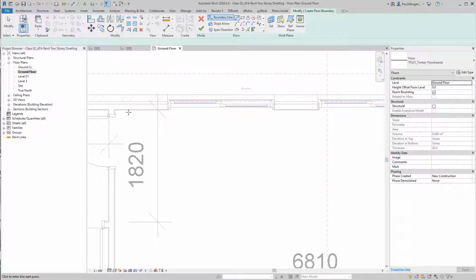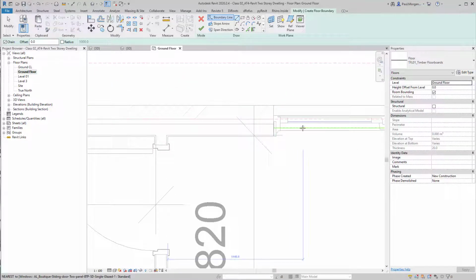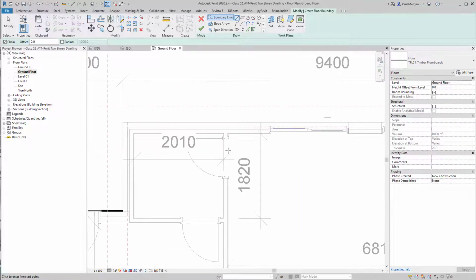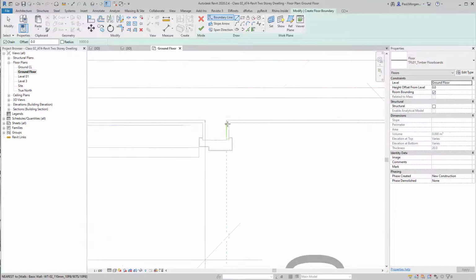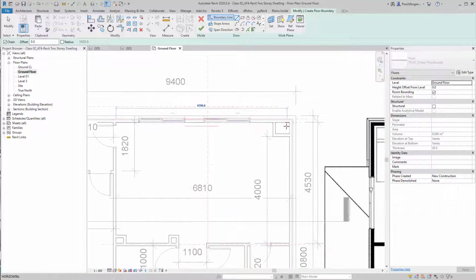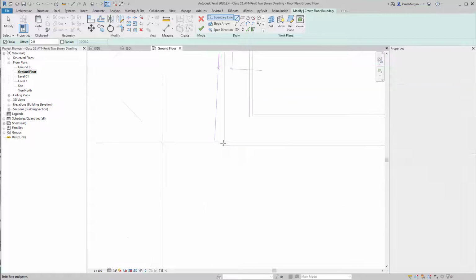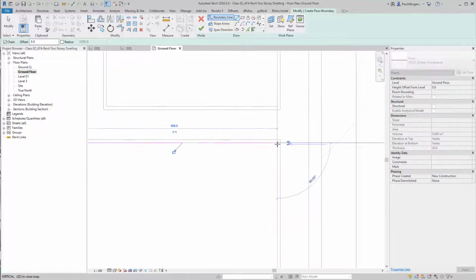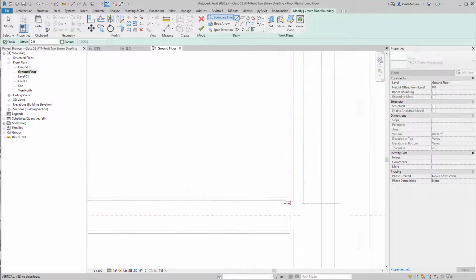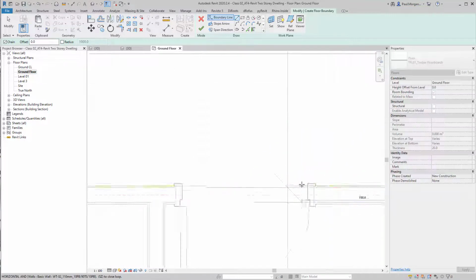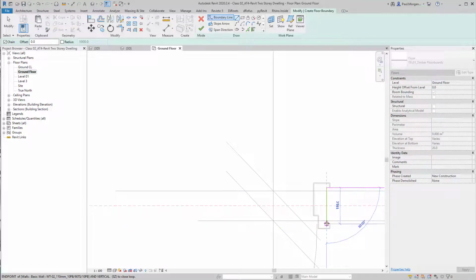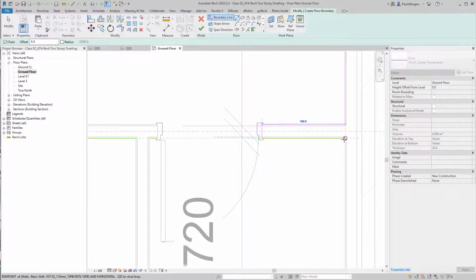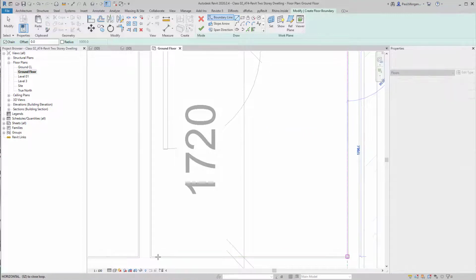You need to carefully, very carefully, draw around the boundary of your walls. So this is the open living area. So I'm going to draw around the plasterboard, and I'm going to follow this around the whole way. And you can see that this will take time because I'm going to need to draw around here. And this is why we did the doors first, because we need to go around the openings for the doors as well, like so, because there'll be floorboards in the pantry.